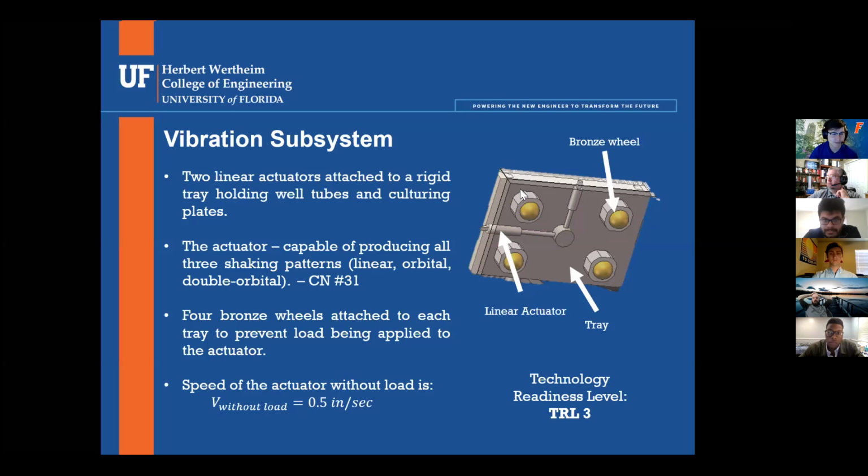If you were concerned with low friction, why didn't you go with Teflon or ultra high molecular weight polyethylene or another low friction polymer? Teflon's got a coefficient of friction of 0.1. UHMW has one of like 0.15. Also, is this solid bronze or oil impregnated bronze?